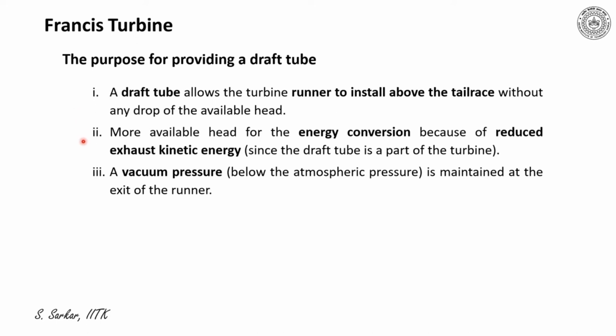The second point is that more energy is available for conversion because of reduced exhaust kinetic energy, since now the draft tube can be considered as an integral part of the turbine. The third point, a vacuum pressure, that is below the atmospheric pressure, is maintained at the exit of the runner because of the addition of the draft tube. Thus, there is a chance of cavitation, which will be discussed later.